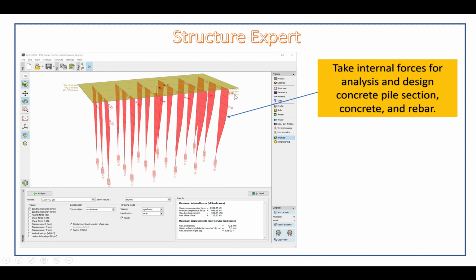Okay, this is the concept of why I talk about the difference between analyzing single pile and group pile for the soil bearing capacity. But for the design of the rebar, it is not different after you get the analysis result. The process is the same.